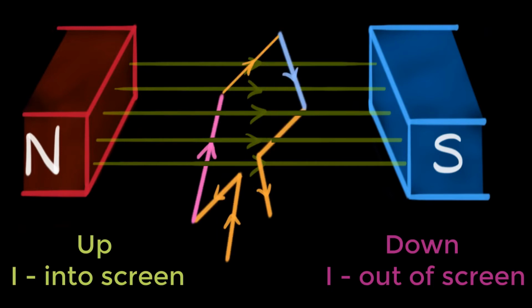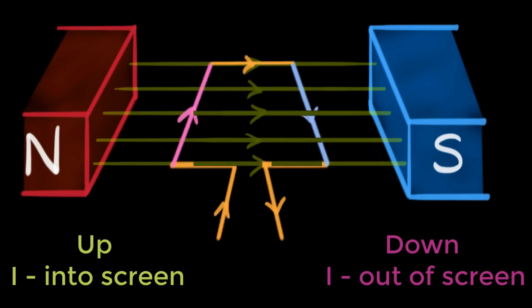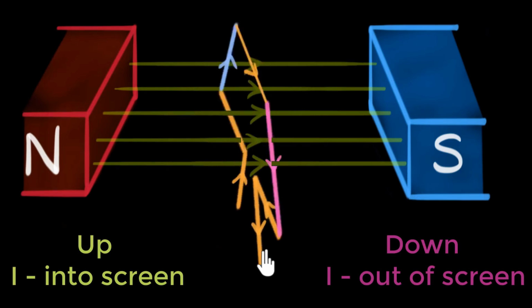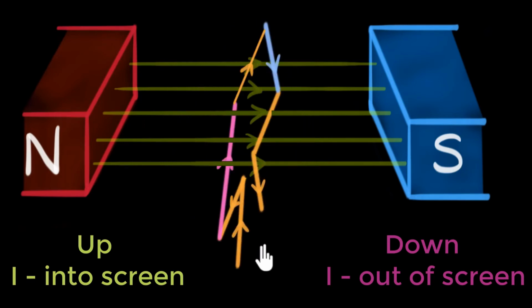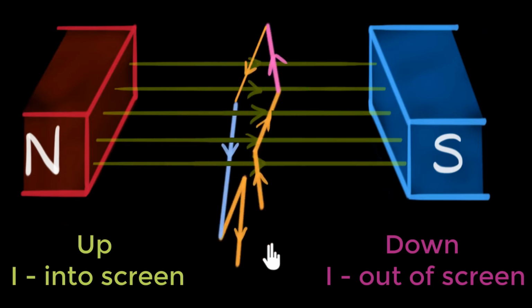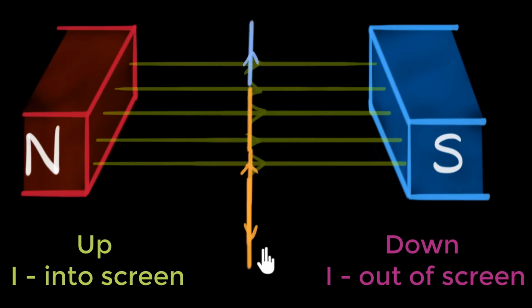And so if you look at the entire animation now, it looks somewhat like this. Every time the coil comes in this position, perpendicular to the magnetic field, the current direction keeps changing. Now, of course, in the animation, I'm pausing the animation when my coil is perpendicular to the magnetic field so that we can see the current flipping its direction. But in reality, the coil will be pushed continuously. There will be no stopping. There will be no jerking motion like we are seeing over here.